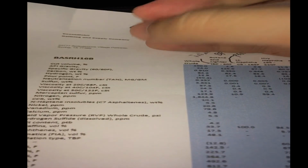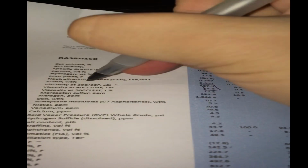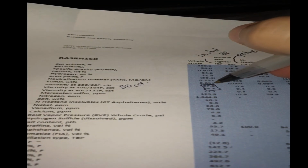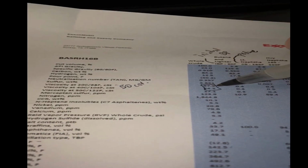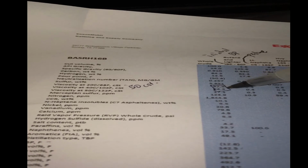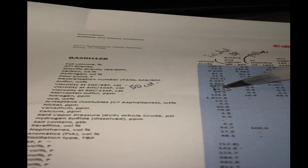Well, let's take a look at our assay again. And we can look at the viscosity at around room temperature of crude oil, which is about 50 centistokes. Here at 20 degrees centigrade or 20 degrees Celsius is about 57.3 centistokes. At 40 degrees, it's about fever temperature, your body having a fever. That's about 24 centistokes.